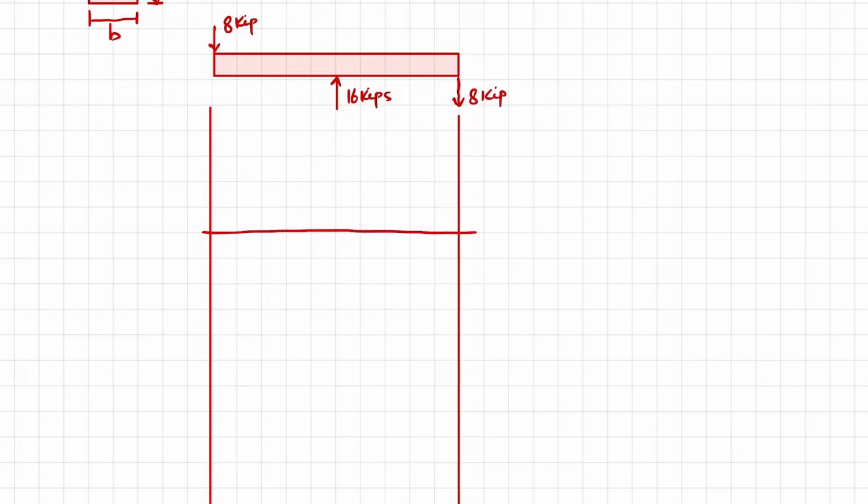Along the x-axis we will take the length. Here we will draw the shear force, and that will be in kips. Each division is, let's say, 4. So 4 plus 4 is 8, and similarly minus 4 and minus 8. Now you can see at this point we have a load of 8 kips, and that is downward, so it will be minus 8.